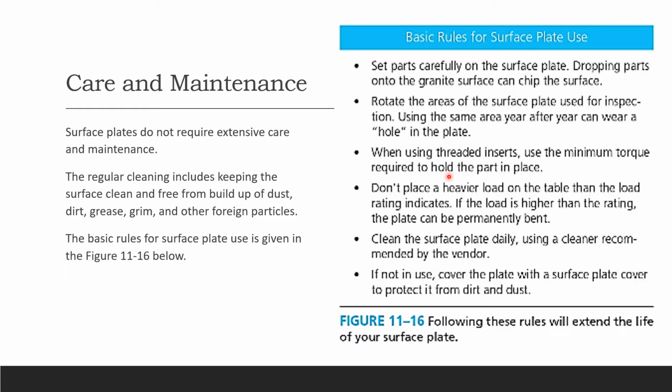When using the inserts, use the minimum torque required to hold the part in place. And don't place a heavier load on the table than the load rating indicates. You can read it. So that's how you use your surface plate.